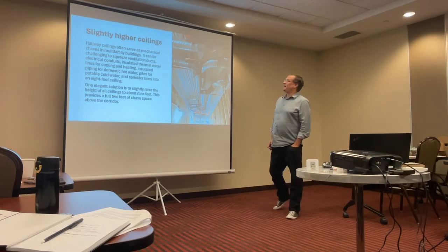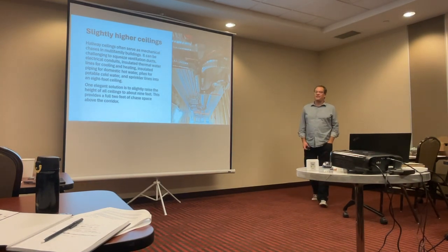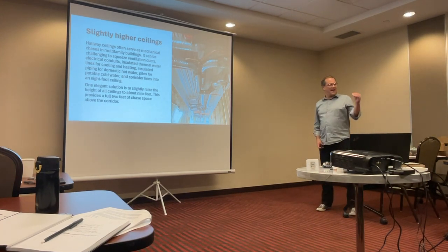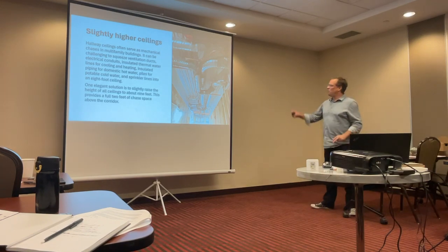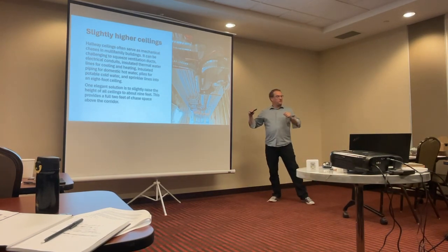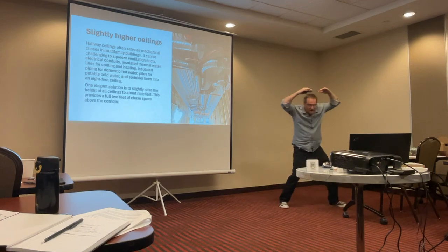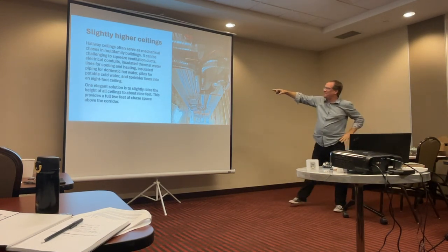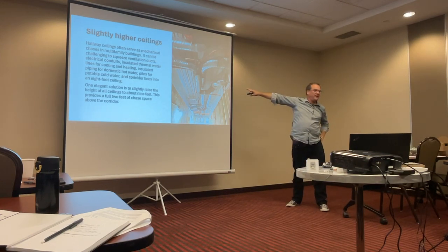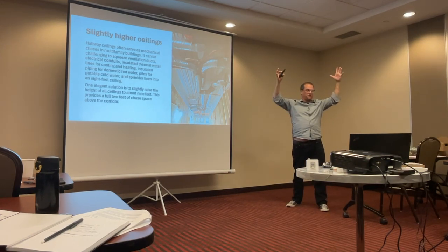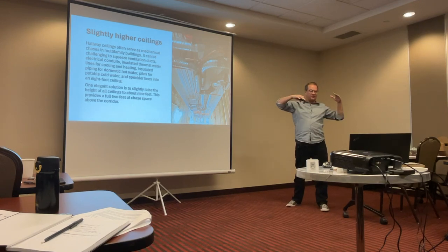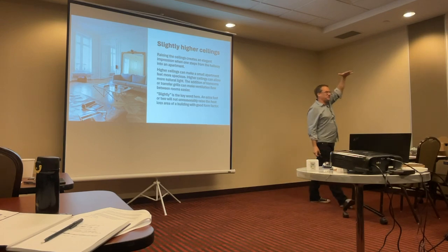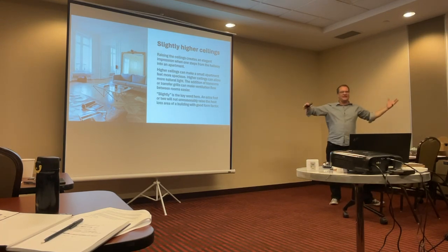Okay, here's another idea I want to put out there for a lot of multifamily: slightly higher ceilings. I'm not talking 14 feet. I'm talking 9, maybe 9.5. It gives you two wonderful things. One, in the hallway, you have space to do what you have to do, rather than hallways where only one person can walk through. Just an extra foot is not going to blow the thermal enclosure of the building, if your height limits can allow it without extra floors. Then once you step from that into the apartment, you feel like you have these huge high ceilings, and in a small apartment, it starts to feel light and airy.